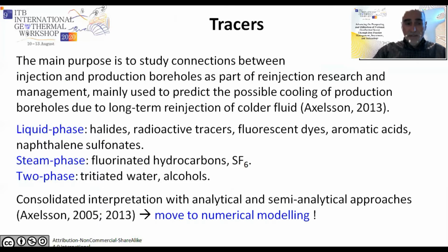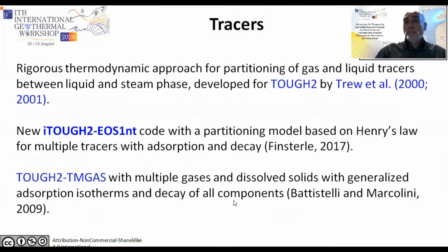Tracers. The main purpose of tracers is to study the connection between injection and production boreholes in order to predict the possible cooling of production boreholes due to long-term reinjection of spent brines. There are tracers suitable for the liquid phase, for the steam phase, and for the two-phase conditions we can find in the reservoir. And there is a consolidated interpretation with analytical and semi-analytical approaches, as described by Axelsson. But we can move to numerical modeling.